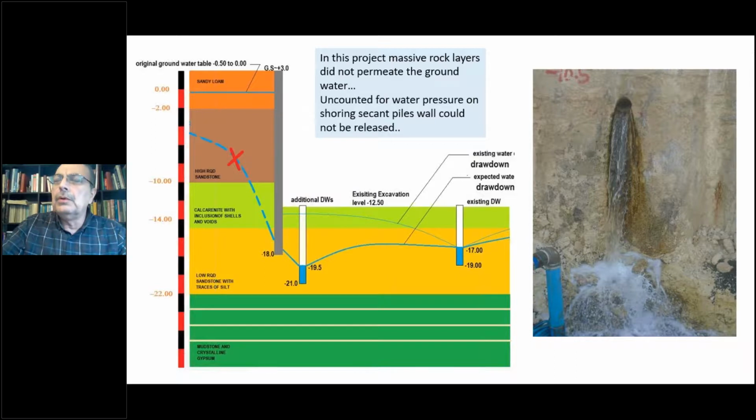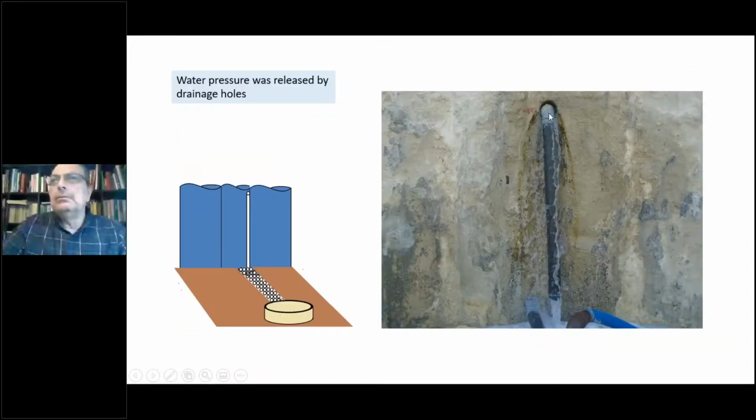The water is flowing, but we need to collect this water in some way. This is not possible to be collected if you don't use the dewatering system. We did a simple PVC pipe, with a deep hole inside, like 1 to 1.5 meters, and some were even 2 meters, to collect the water. So releasing the pore water pressure at the top part stopped the deflection.